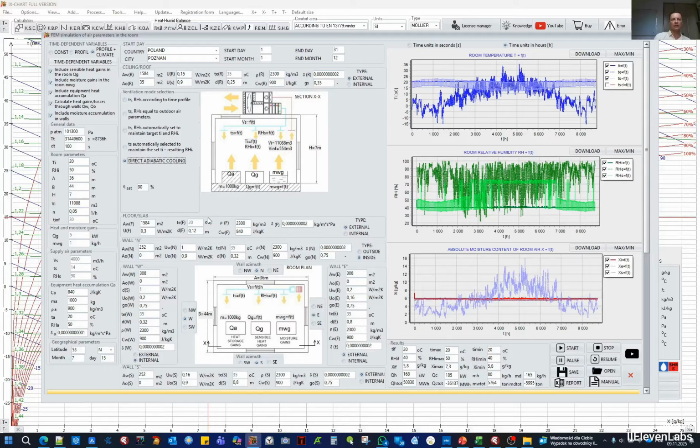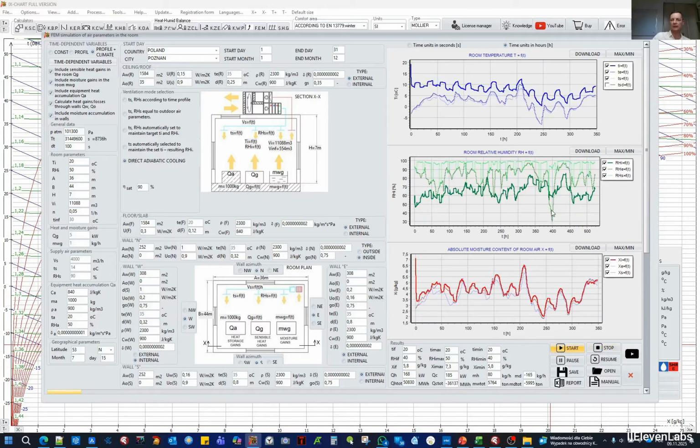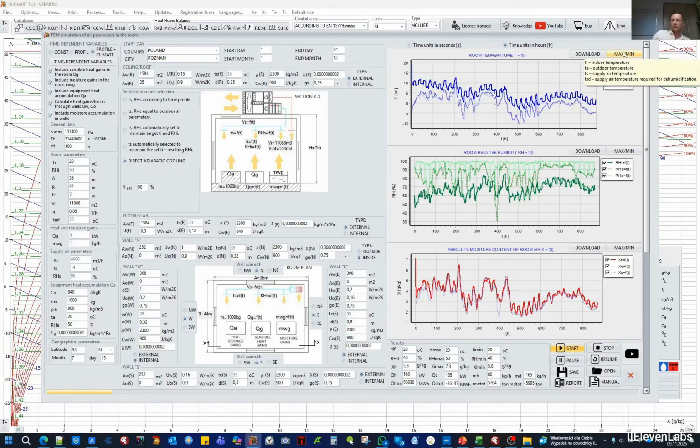And the limit here is the wet bulb temperature that we can achieve for a given combination of intake air parameters. So this efficiency of 90% simply tells us how much of this air will not actually undergo such humidification, or on this curve of adiabatic humidification, where we stop. Okay, so as not to prolong, I am starting such a simulation, and here I will also show how it shapes up.